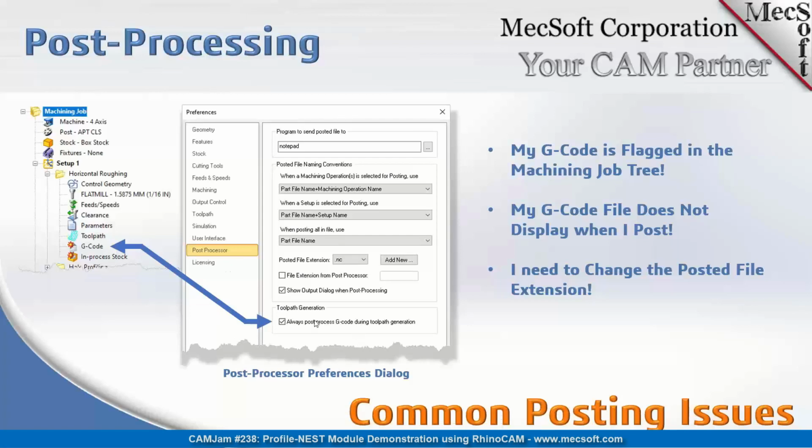So if you don't have this checked and you generate your G-code, this icon will flag just to let you know that the G-code was not auto-generated. If you see this flag, as long as your folder itself is not flagged, that's fine. If you see a flag on your folder, that means you need to regenerate it. If you just see a flag on the G-code icon, you can go into here and check this box to always post the G-code, or you can just ignore it if it's just one flag on the G-code item.